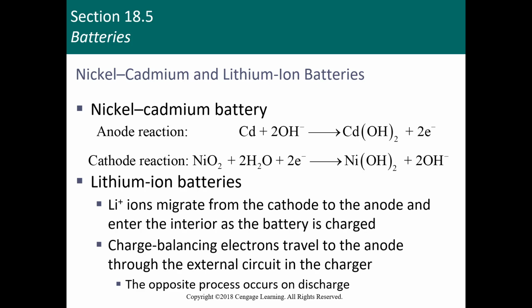One of the other things, can I overcharge a lithium ion battery? No, you can't. The only danger you have from overcharging it is if it gets hot. If it gets hot, then yes, charging it is going to cause problems and it'll cause damage. That's swelling. If you ever notice an old phone starts popping open, swelling is actually due to you making lithium ion crystals, typically because you charged them hot. You will notice that the newer phones typically run their fan when charging quickly, and that's to keep it cool.